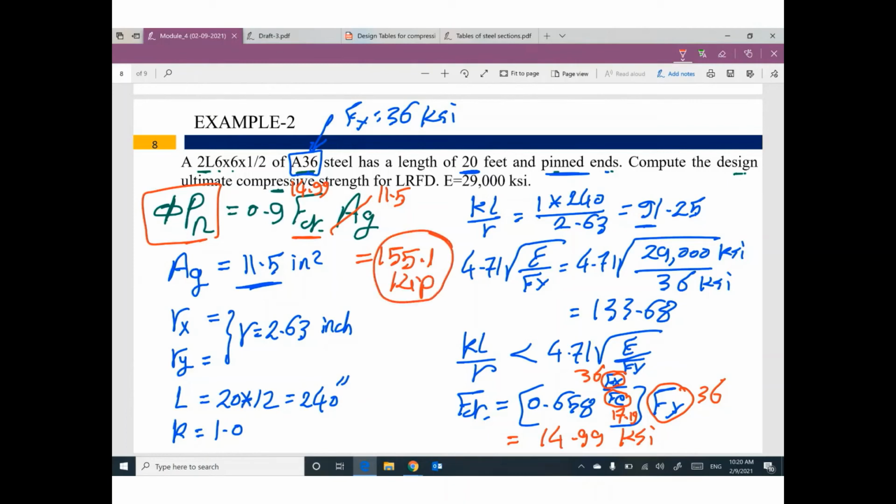Very simple. Just have a cross section and I can tell you the design compressive strength of this member. Please make sure after you are done with this calculation that the P ultimate from RISA analysis or from structure analysis is smaller than or equal to the design compressive strength of the member, to make sure this member is safe against the applied load.